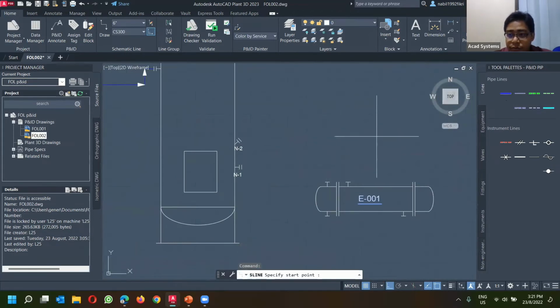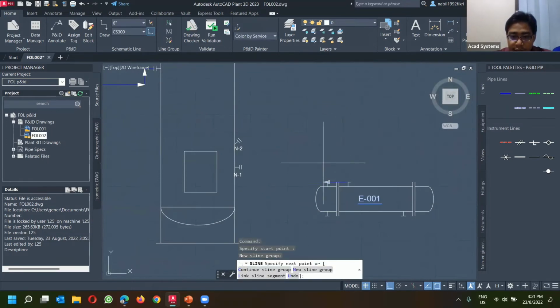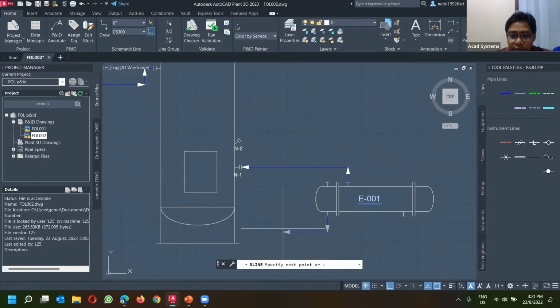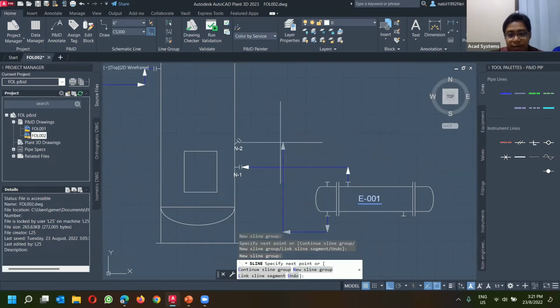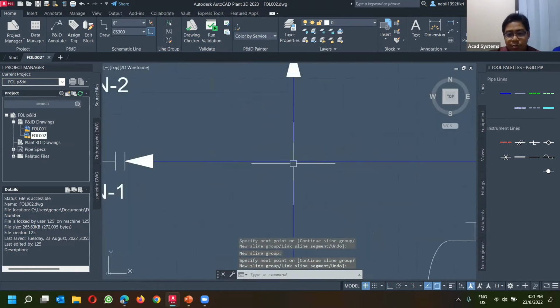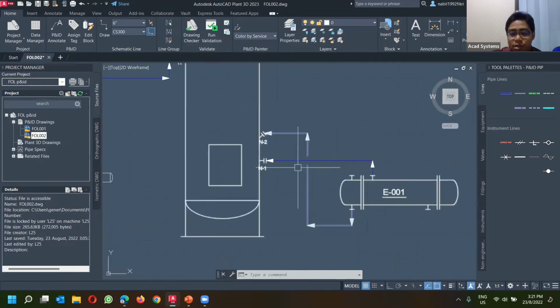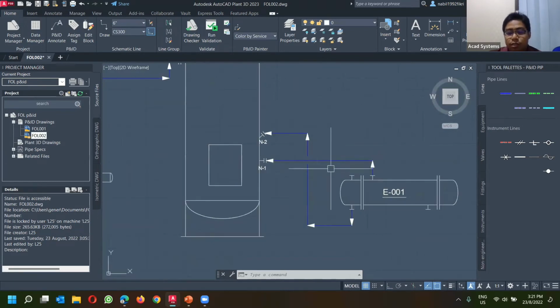Let's say I click a line from here and connect it to this line, and then I have another line at the below over here, which will intersect with the other line, and I'm connecting to this one. So you can see it's automatically creating the gap over here. Right? It's automatically creating the gap from here. So you should be able to notice that this line is not connected, but rather it is actually passing through without being connected together.